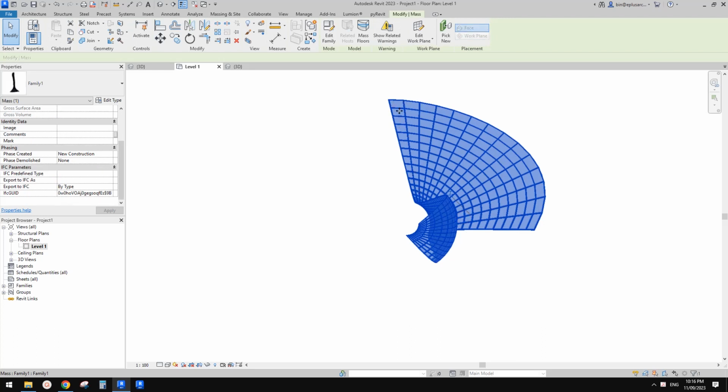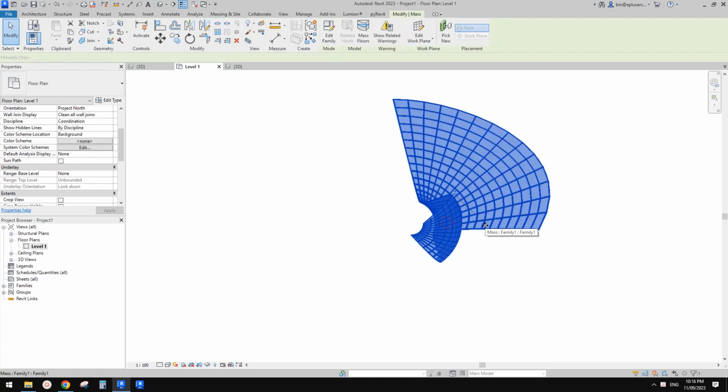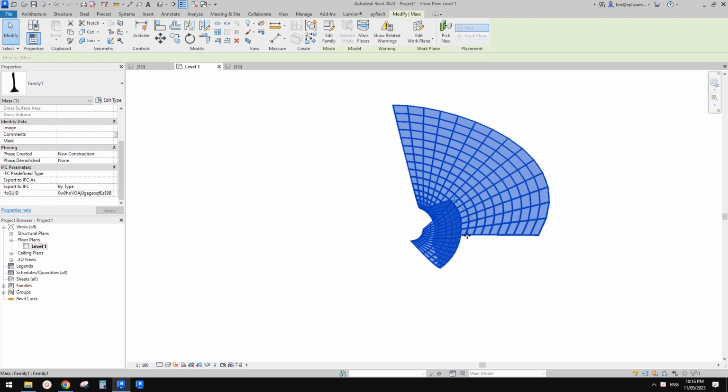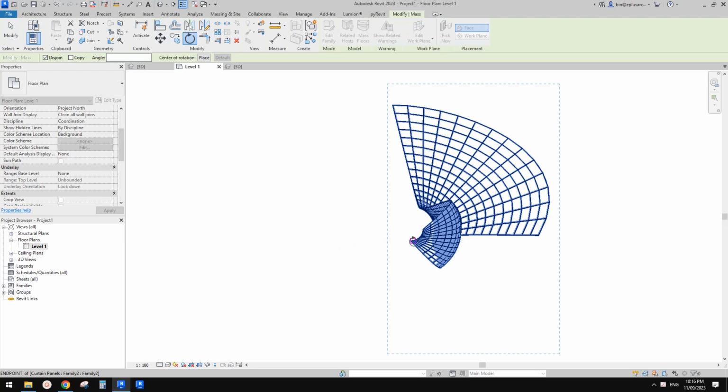Yeah, I think we should probably adjust this one so it's not more than 90 degrees. But anyway, let's try. I'm going to rotate this, and I'm going to use this center point. I type SC, to pick the center point of any of these arcs.